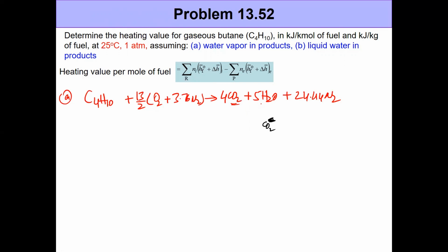Now there is a very quick trick for determining the coefficients for CO2 and H2O, and it's simply that when we just have CO2, we don't have any carbon in any other product on the product side, meaning there's no CO or no unburned hydrocarbons or something. Then all the carbon is getting converted to CO2, right? So if you have 4 atoms of carbon here, that's what we'll have here. In CO2, you just have 1 carbon. So basically you need to multiply it by 4, right? So this number goes in here.